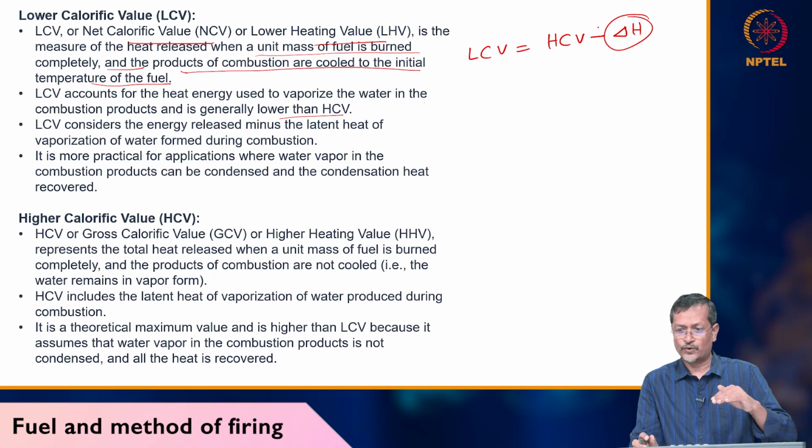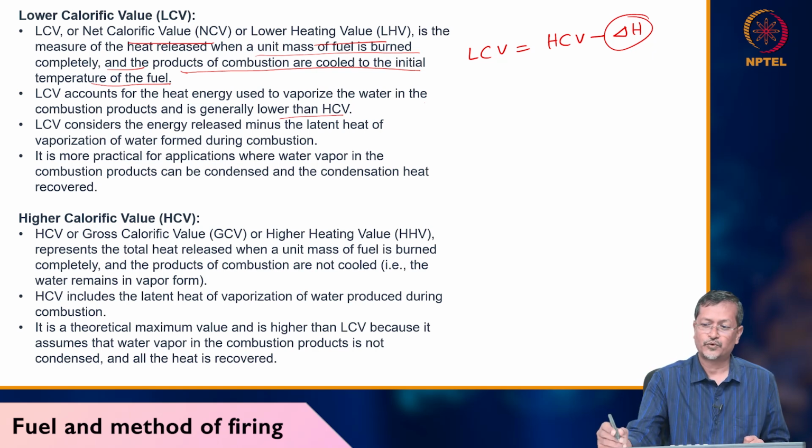LCV is the lower one because, when you burn fuel, if there is any water content in your fuel, that will take some heat. It takes latent heat, as well as sensible heat, and that heat you cannot use for your proper purpose, because when it is in gaseous form it carries this latent heat within it and goes out. So that is not useful for you. That portion you have to subtract, then you get your LCV.